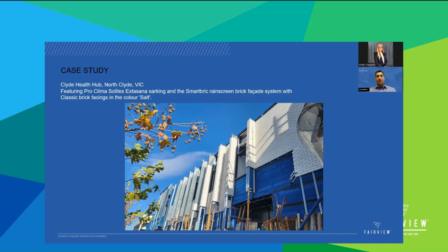Okay, Paul. Thanks, Paul, for your question. Paul is asking if we do require fire breaks between floor levels. In principle, yes. When you do have an open air cavity, what you need to do is try to compartmentalize it. So in order to avoid the chimney effect, good practice is to use horizontal fire cavity barriers at floor levels.